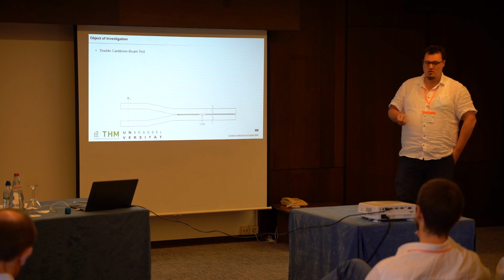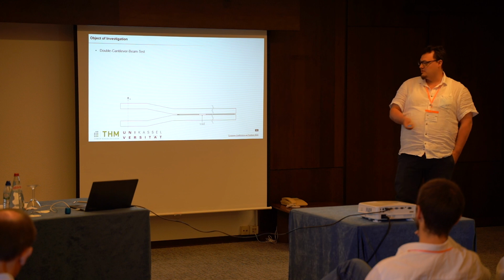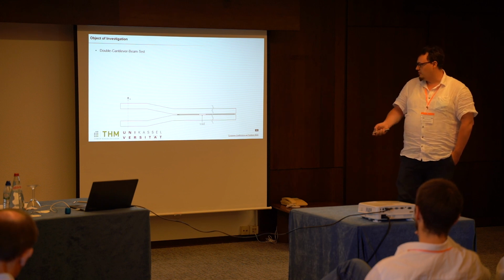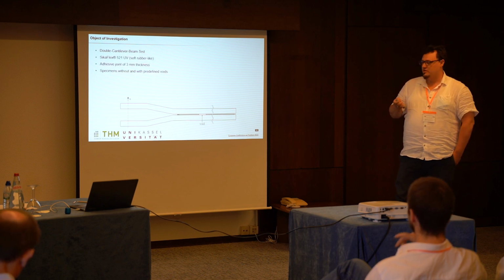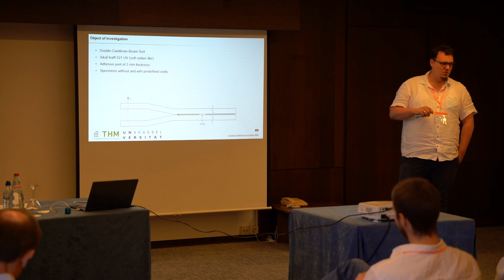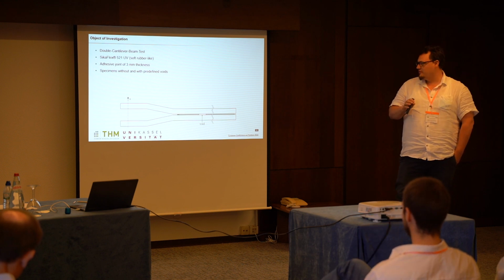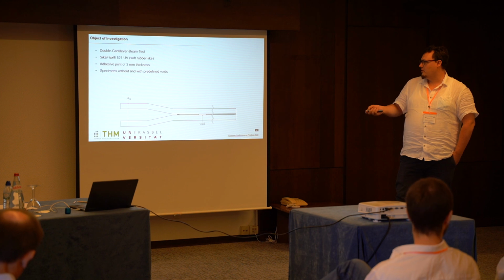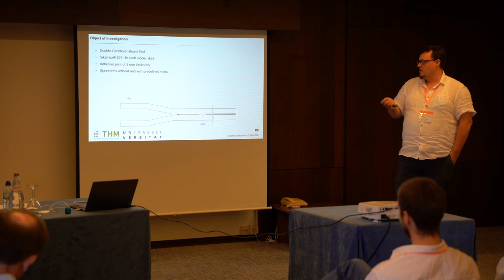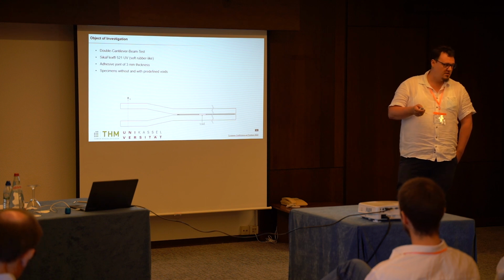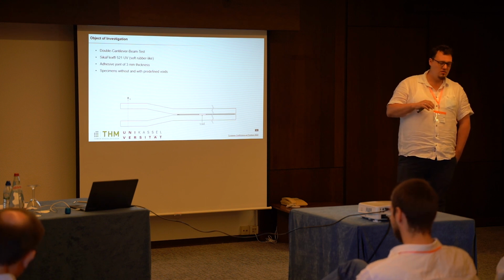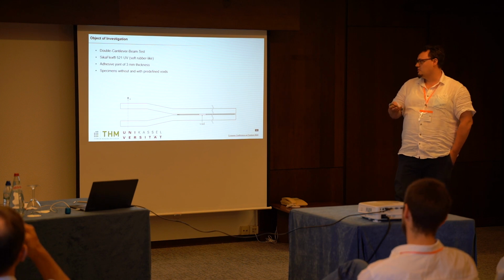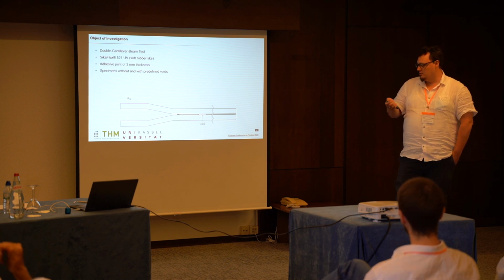For this we performed double cantilever beam tests. The specimens you see on the bottom of the slide. We used the Sikaflex 521, that's a soft rubber-like adhesive. For the joint thickness we chose 3 millimeters, and we prepared specimens without voids and with voids, and a width of 40 millimeters.